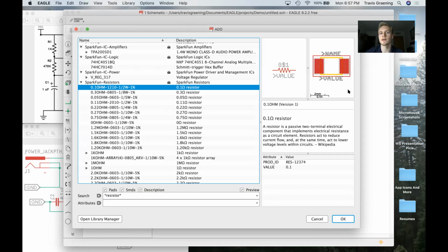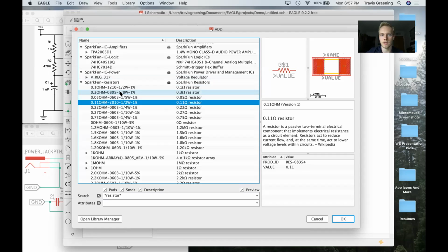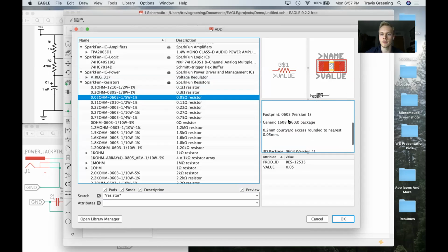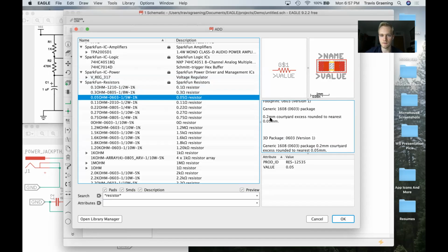Today we're just doing through-hole parts. This is what a surface mount part looks like. So if you see this when you're looking for resistors, this is not what I'm looking for in this particular design. That's what a lot of these look like right here, but they're all varying sizes. There's actually a little description of it right here, the package size, and so on, and actually the dimensions of the part.